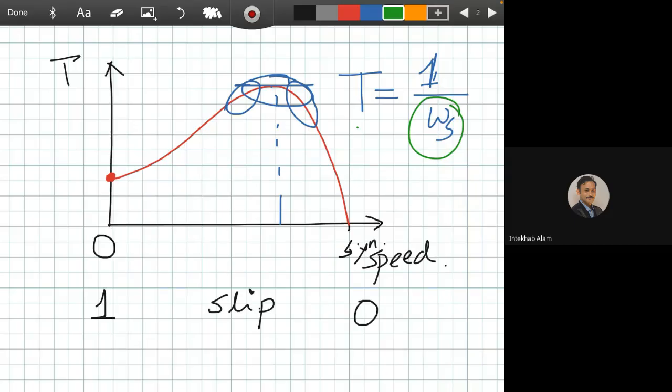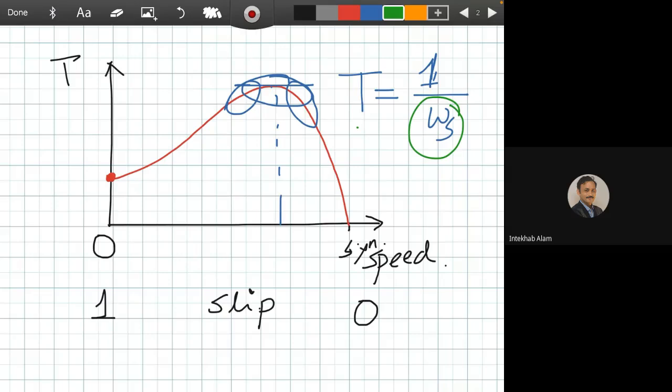Can you understand this point? If we decrease the frequency, we can increase the torque. If we increase the frequency, we reduce the torque. So torque is something we can manipulate by changing the input frequency. It actually changes in a double fold, not just with omega. You will find another two parts, xs and xr, in that equation. Can you recall?